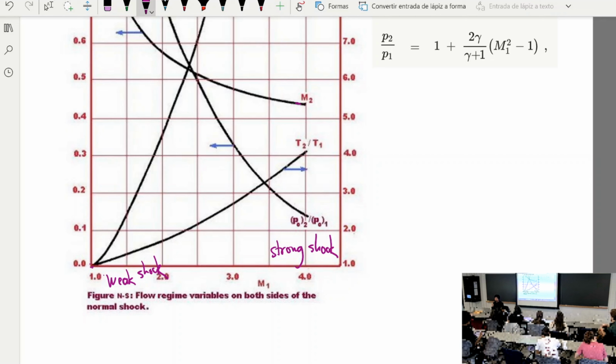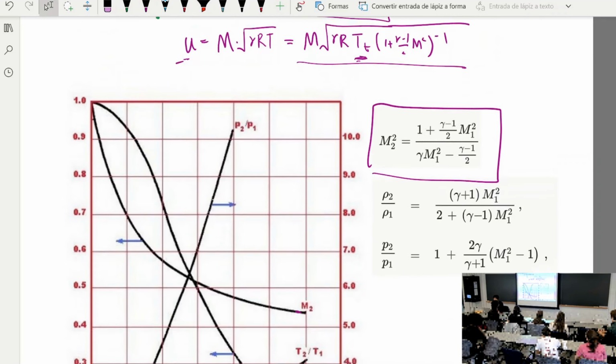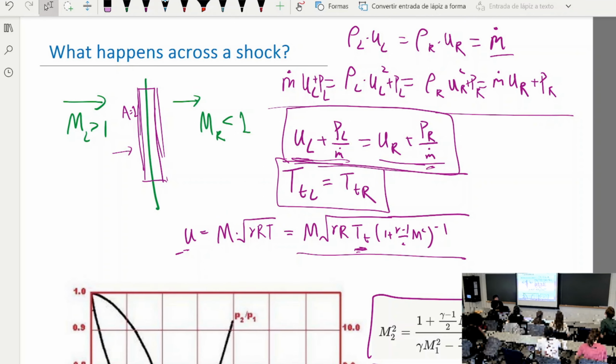And when I say Mach number upstream, I'm looking at a frame of reference in which the shock wave itself does not move. Right? Like all these conservation equations we are using to derive these are steady state. A steady state control volume around this. I mean, if the shock wave moves here and here, then this conservation may not be true anymore, right? Because then there is a change in how much momentum there is in the control volume. Okay.